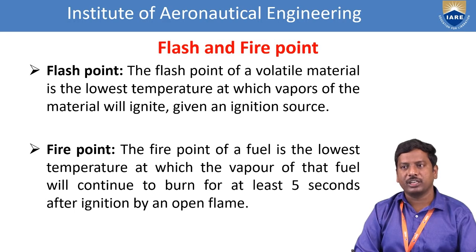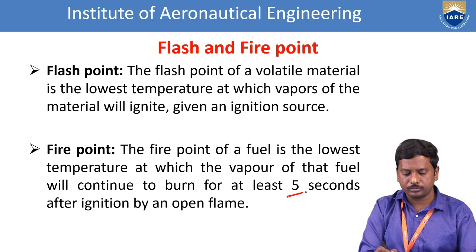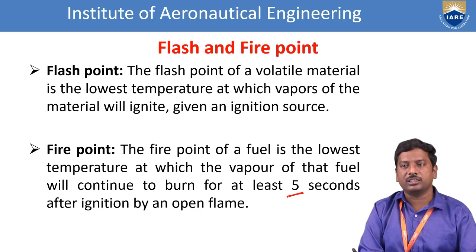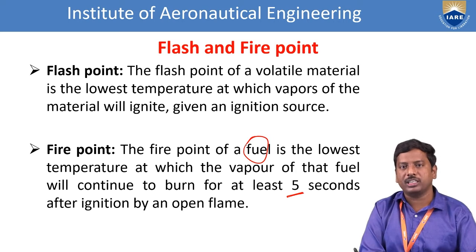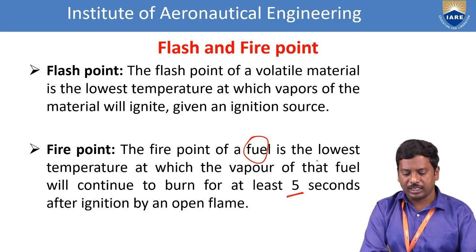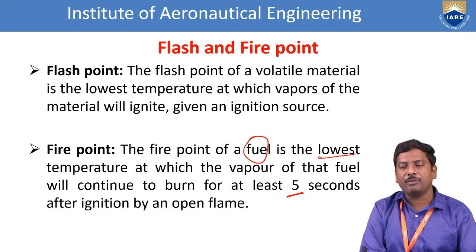After that, we see the fire point. The fire point of a fuel is the lowest temperature at which the vapor of that fuel will continue to burn for at least 5 seconds after ignition by an open flame. Fuel is nothing but a hydrocarbon, that means petrol, diesel, kerosene, or any hydrocarbon material. So this is about the fire point.